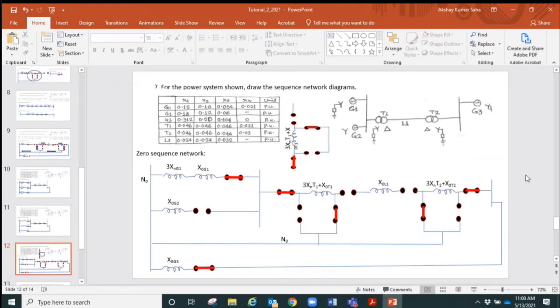But again, this doesn't show the fault point on the system, but you can think of any fault maybe on the line or on either of these two bus bars, and determine the equivalent reactance, checking in which way you can arrive at the neutral bus starting from the fault point and how many ways there are, and then taking that series-parallel combination into consideration.